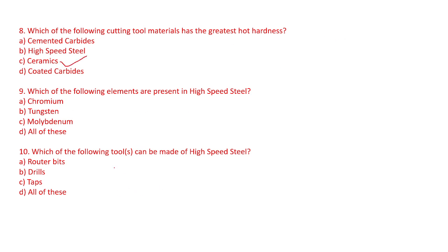And we have also seen the usability of ceramic cutting tools. One advantage is that it uses negative rake angles, so less force is applied directly to the ceramic tip. Moreover, it takes a large nose radius and larger side cutting edge angles on the ceramic insert. Those are a few of the usability advantages of the ceramic cutting tools which are being used.